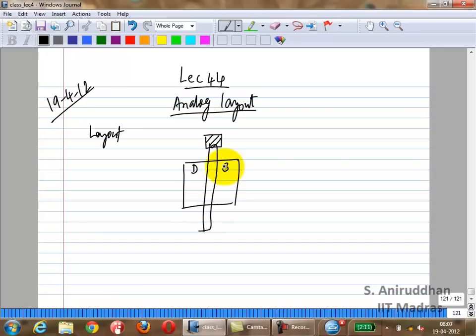You also need the option of adding external metal connections to the gate, drain and source. The way you would normally do that is with what are called vias or contacts. Vias are usually between different metal lines, while contacts go from the substrate or poly to metal lines. Then what you would do is something like this. Let us say this is a metal line, this could be another metal line, and this could be a third metal line. These should be the gate, drain and source connections.